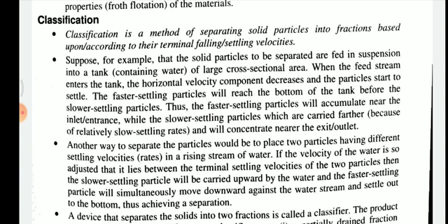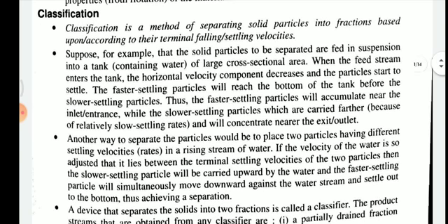In simple words, the particles whose size is greater or which have a greater density go quickly to the bottom, and the others which have a low density will settle slowly. Okay, so the faster settling particles will accumulate near the inlet entrance.